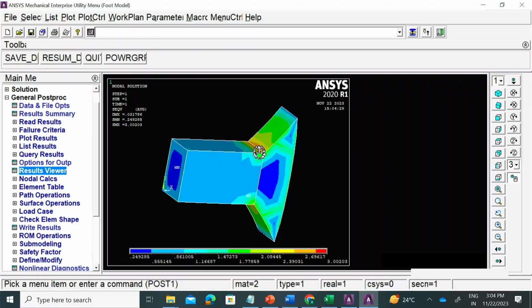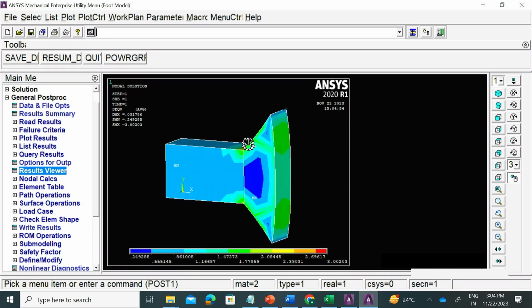There is another way you could have done this probably. So what I can do is like just select the surface on the right and extrude it. That creates another body, right? Of course you cannot get the complex shape, but it could have an extruded body, where you have two volumes, one is an extrusion of another, and they are also perfectly connected because it's sharing a common surface, right? So whenever there is a common surface sharing, those bodies are connected.